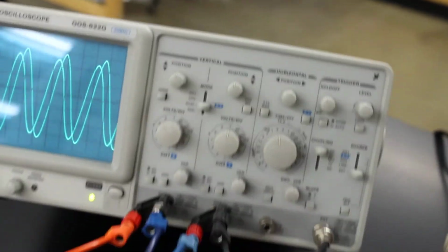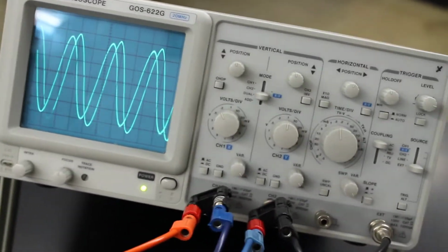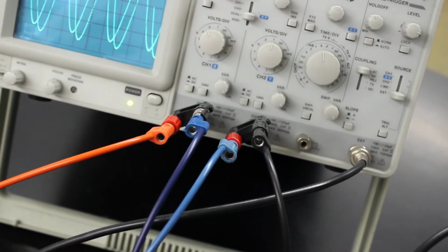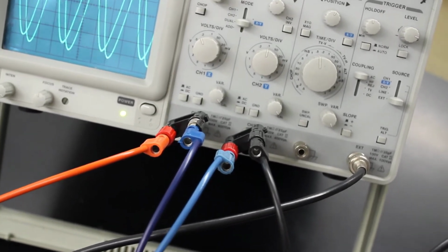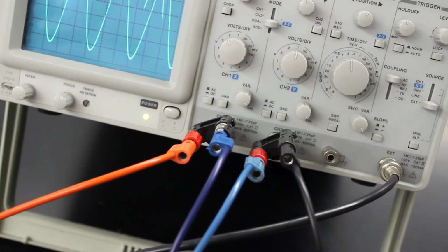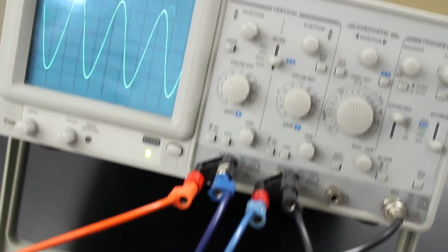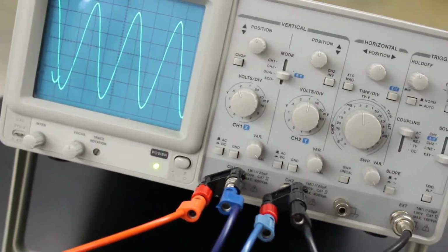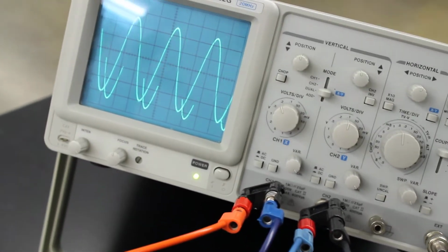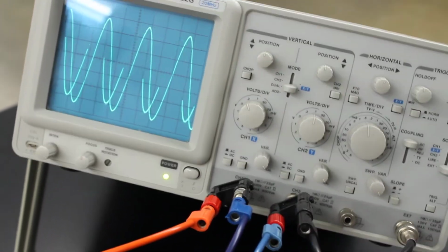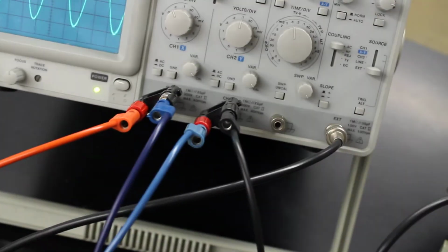Now what's different is, instead of having 2 voltmeters, 2 multimeters, we now have an oscilloscope. An oscilloscope is nothing more than a voltmeter with a graphic output, so you can look at the shape of AC signals. With a multimeter, all you can do is get an average of those time-varying signals. With a scope, you can actually see them. And so what I have here is channel 1, which is this one here, hooked up, back over here to this orange one, to the source.